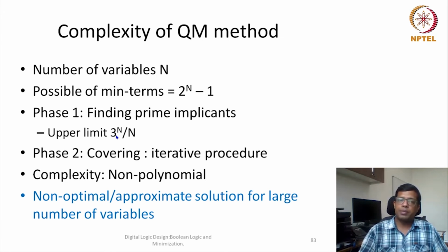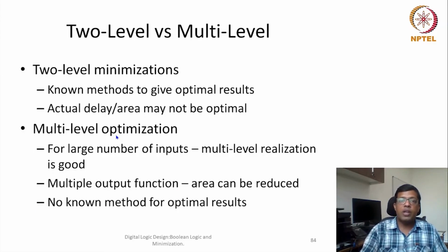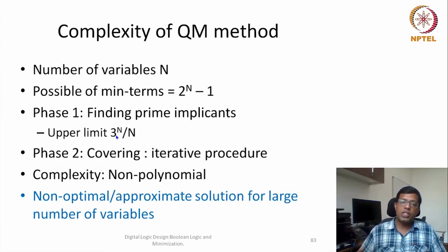This will come from the algebra. In our previous module, we saw there were a couple of stages where we tried to remove redundant terms, add some terms and then remove some terms, and remove variables and literals. All these logic transformations would be done one by one and iteratively, so that we reach near an optimal solution. If we reach a solution from where we see that no further cost can be reduced, then we settle for that particular solution.